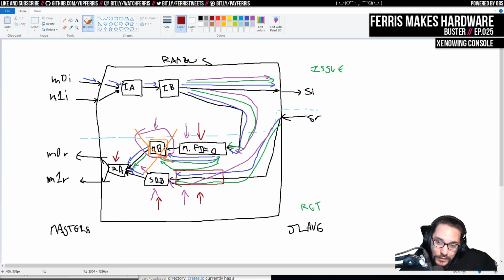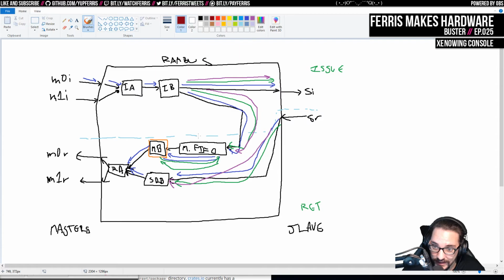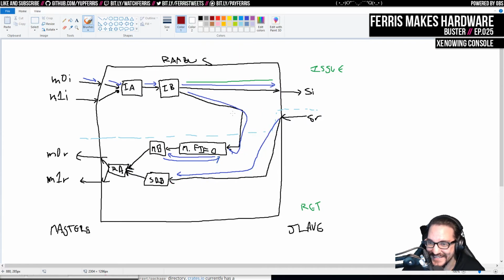The arbiter can issue a read to both, and then data will come out. So in theory, this one will always lag behind, but I think it works out. I think it really just introduces a single cycle of latency up front, and then after that, this FIFO is one cycle ahead, but it should still work itself out. We should still achieve good throughput. That's the point, even though we have an extra cycle of latency, which we actually incur anyway by having this buffer. So I think that's what we need to do.